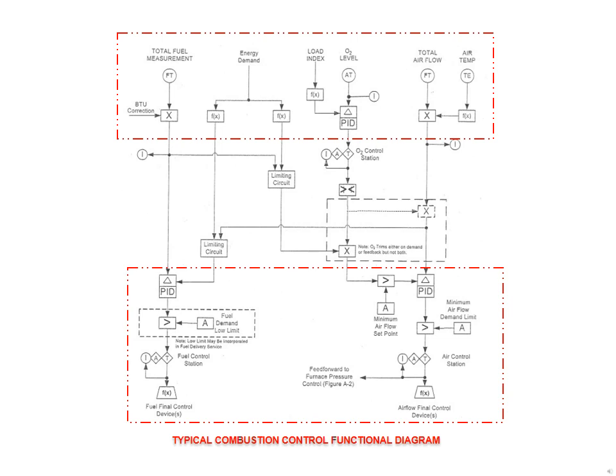The positioning system is simple and fast responding, but it cannot compensate for varying fuel characteristics, atmospheric conditions, dynamic characteristics of the fuel delivery equipment, or the imbalance of fuel to air ratio during rapid load changes. While metering system measures the actual fuel and air delivered to the boiler. The measured flows are used in feedback control schemes to precisely regulate the fuel to air ratio.